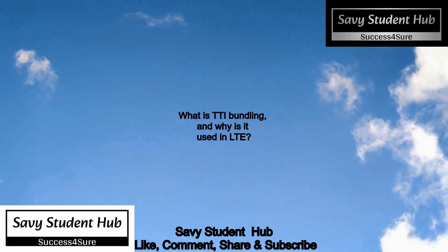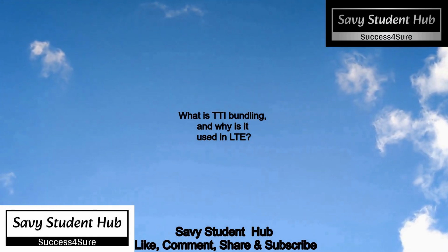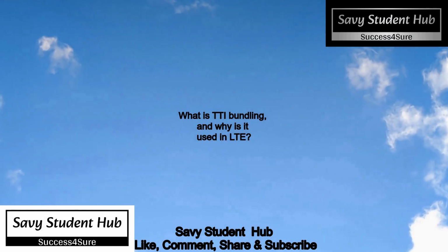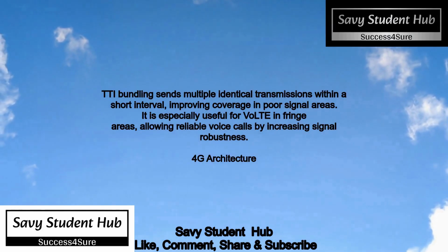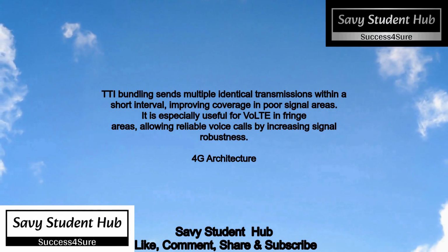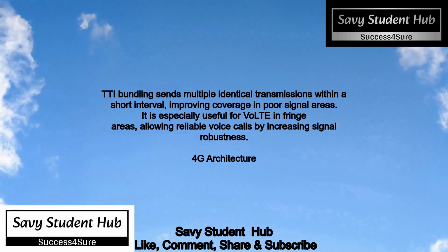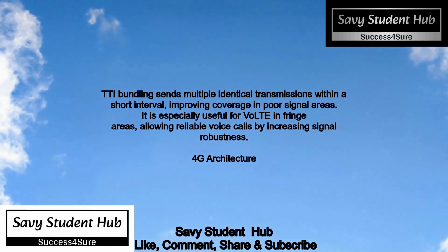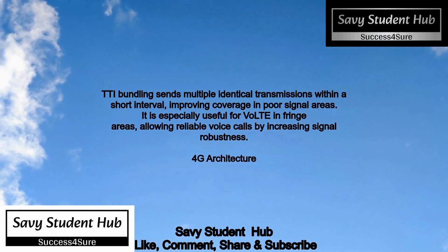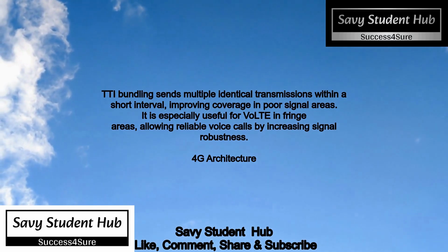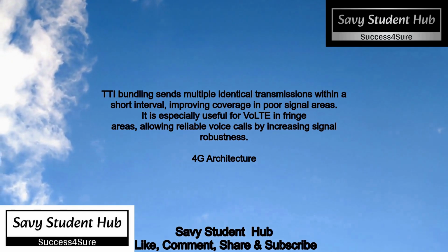What is TTI bundling, and why is it used in LTE? TTI bundling sends multiple identical transmissions within a short interval, improving coverage in poor signal areas. It is especially useful for VoLTE in fringe areas, allowing reliable voice calls by increasing signal robustness.